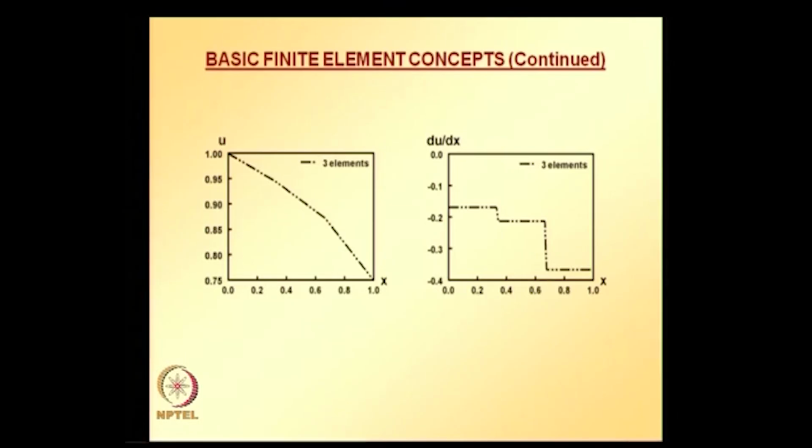So, what we did basically is key concepts are introduced. Here are the development of element equations and assembly of equations to form the global equation system. So, this is the new thing that you learned in this lecture, and it is necessary to develop element equations only once for a class of problem. To get a numerical solution, all that is needed is to substitute appropriate numerical constants.